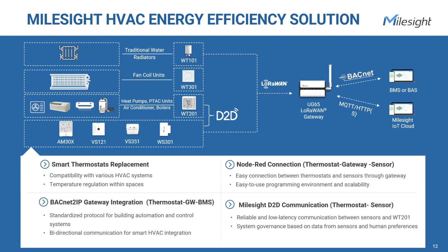The more recognizable approach to smart HVAC controls is the smart thermostat. This smart thermostat approach is lower cost, easier to install, includes local control, and usually requires add-on sensors for enhanced visibility. While smart thermostats are already well known in the residential space, those same devices can be deployed at scale in the commercial space. In your office, the way this works is your HVAC is wired to your thermostat, which is replaced by a LoRaWAN connected smart thermostat. It is paired with a LoRaWAN gateway separate from your on-site network.